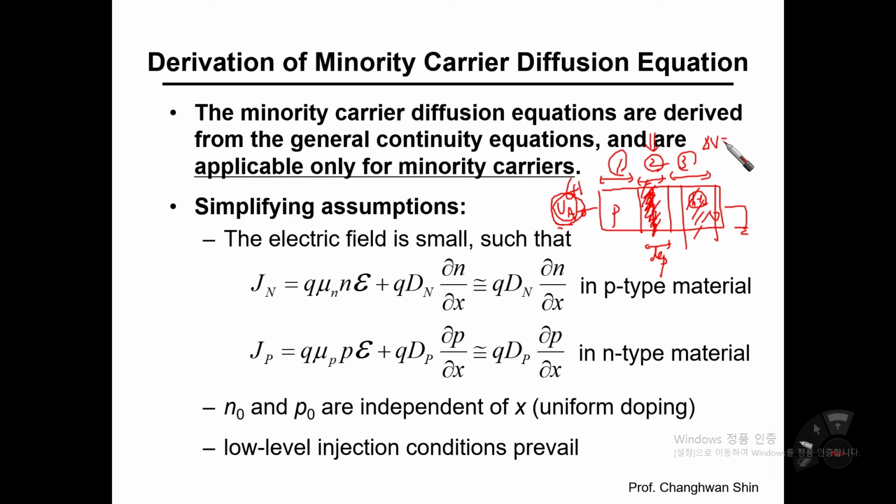The voltage difference is zero in these areas. We are going to learn it later, but this area is named the quasi-neutral region, simply QNR. In the quasi-neutral region there is no voltage drop, meaning no voltage difference, from the edge of the depletion region to the edge of the material.